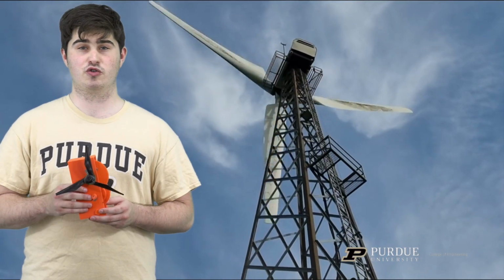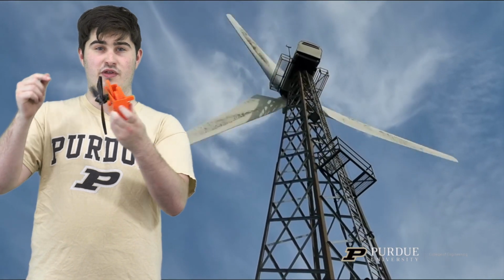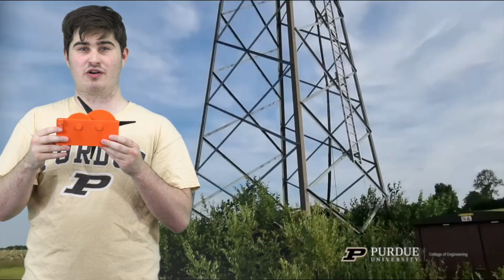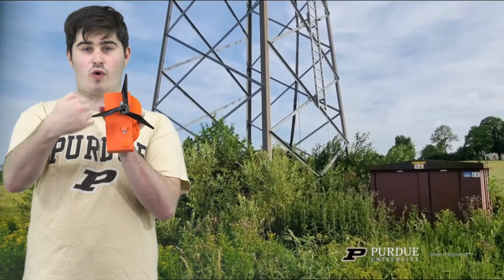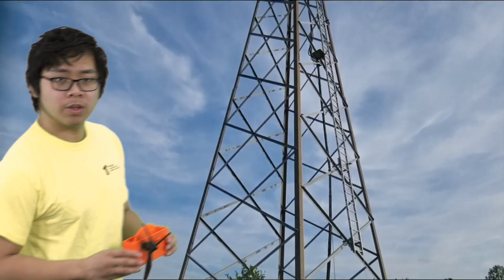We used a two-stage spur gear system, one set with a 100:17 ratio and another with an 80:17 ratio, multiplying together for a total ratio of approximately 2.77:1. That means for every one rotation of the turbine blades, the motor spins 30 times faster.